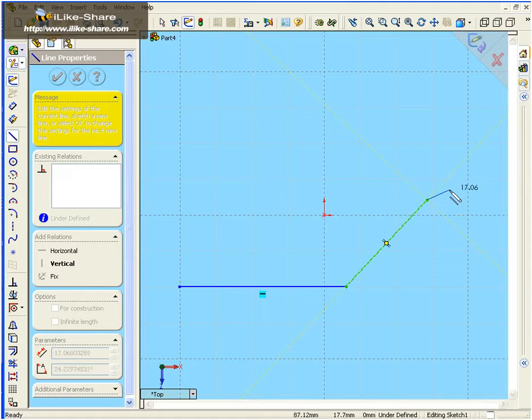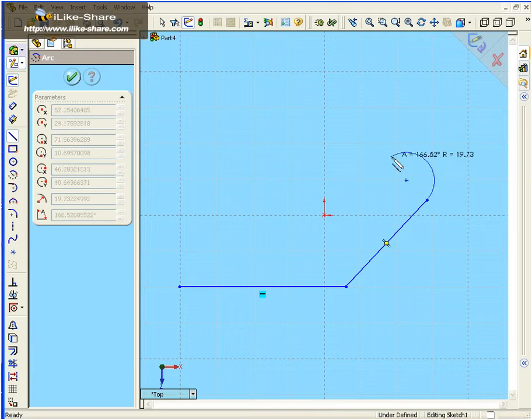Now let's create a tangent arc. In order to activate the arc tool, drag the pencil tool over the last point. Now the line tool becomes the arc tool. You'll see a blue dashed line following the line tool. This line represents the actual geometric relationship. In order to change the direction of your arc, move the arc through the point of origin again.